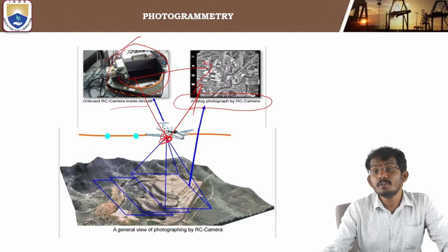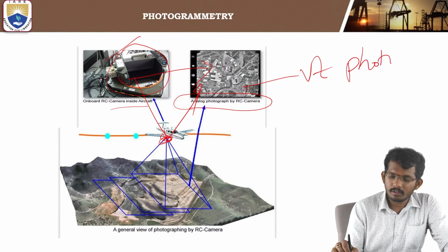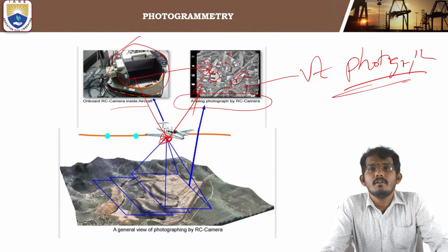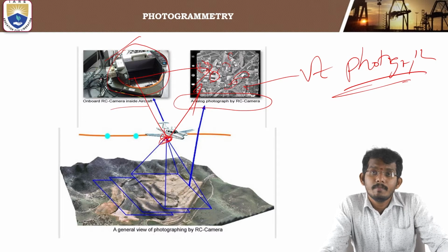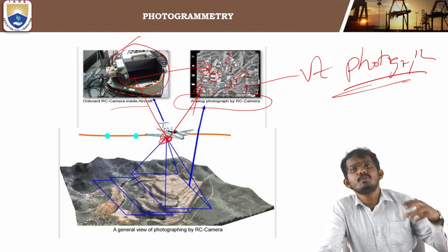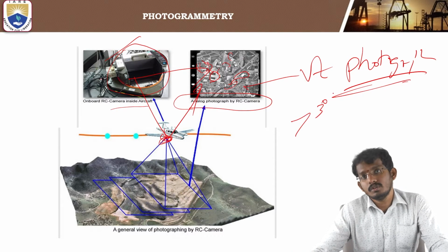Is it a vertical photograph or an oblique photograph? I'll say it's a vertical photograph only, because I can see only the top views. I can see some rectangular, pyramid or block, and triangular structures in this photograph. Hence it is a vertical photograph. If it were a high oblique photograph, I would see only a very precise structure with the atmosphere, as if zoomed in. The camera axis is more than 3 degrees in the case of oblique photographs.